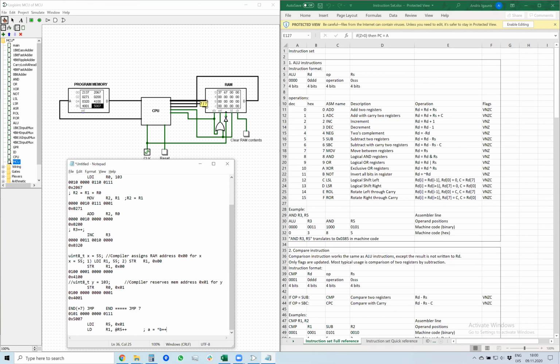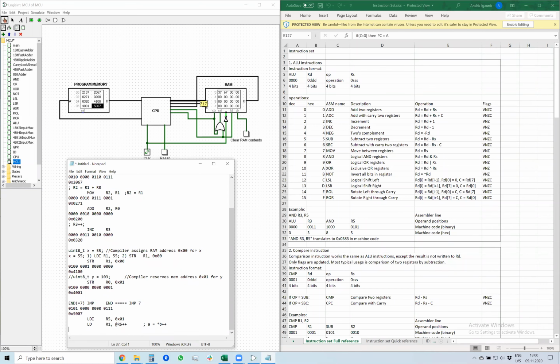Processors have this hardware acceleration so that you can iterate through an array faster. You don't have to write that R1 is equal to the value pointed to by R5 and then increment R5, which is another instruction, another clock cycle.